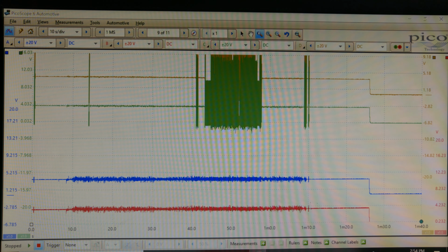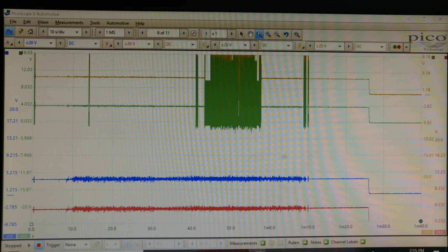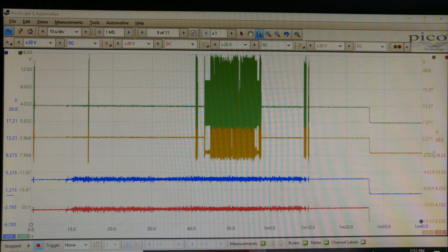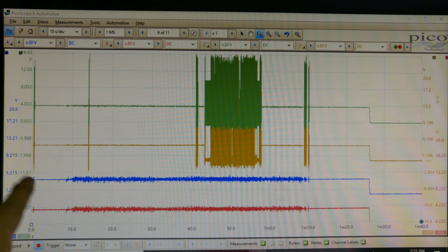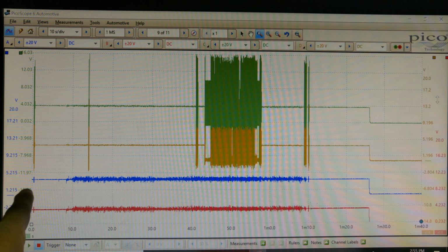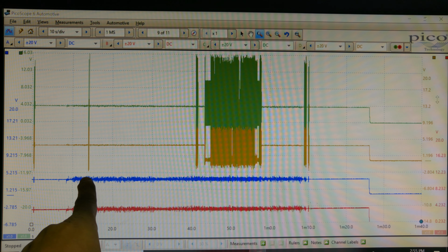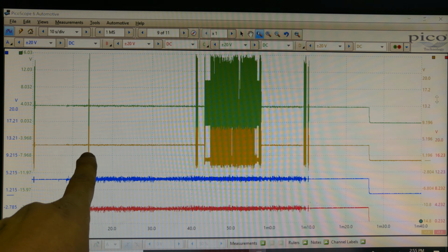After we lost the reverse, I did another scope test here, and this is the result, and I will go through it with you so we both can understand what's happening. At this point, just follow my finger for now. At this point I had the car stopped, and that's when I started the car, right here, and they're all sitting at 4 volts like they should.